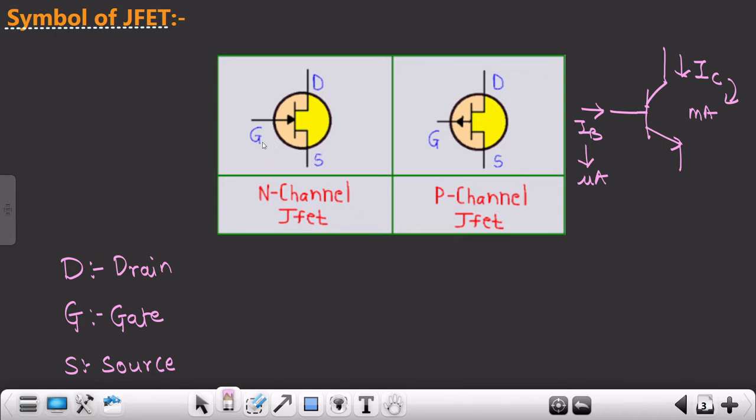On a similar note, we are going to see the JFET as well. Basically, over here, instead of current, we are going to provide a small voltage. Long story short, in case of BJT, we were providing a small current, but in case of JFET, we would be providing one small voltage, which will provide the magnified form of the input signal, and our input signal is a voltage. So at the output side, we will get a magnified form of the voltage.